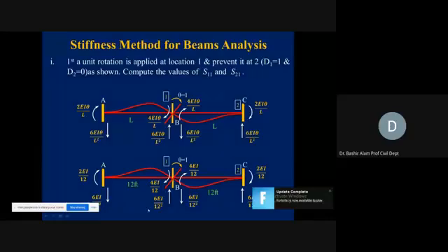If you have a red pen, you should make these two comments here with this sketch. You should draw this bottom sketch, clearly showing these member end actions, and write that this will be used for generating the first column of the stiffness coefficient matrix and the first column of the AMD matrix.